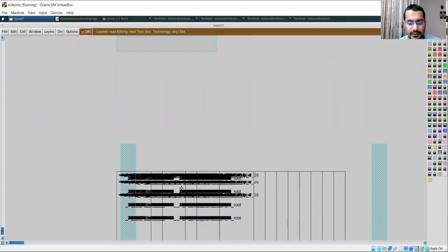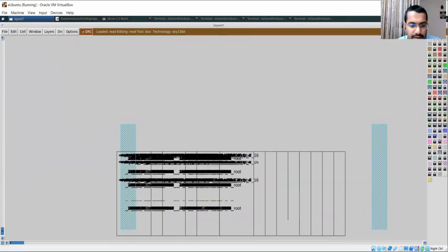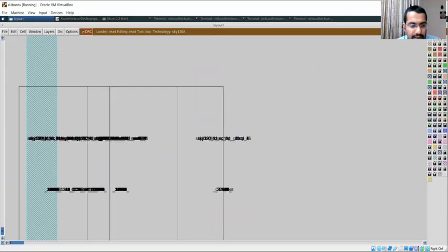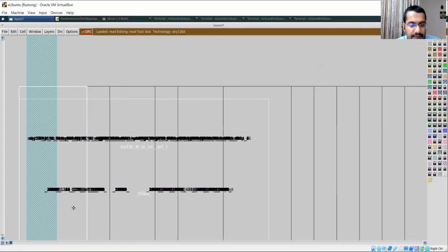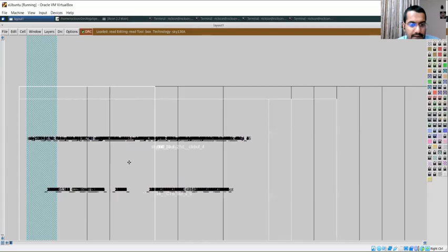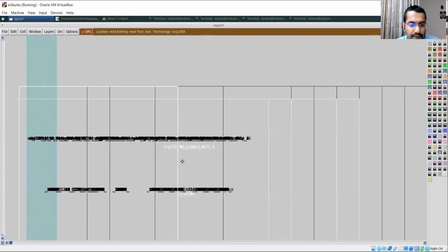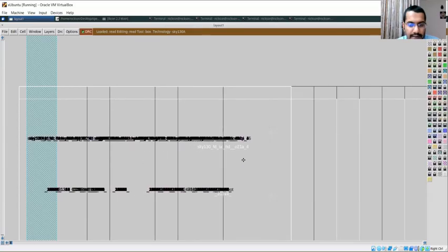So we will do one more zoom. I think we can see now. Okay, so let's see what these are. I will move over one of the boxes. I will do an S. So it's already displayed there. Sky130 buffer. So this is a buffer. Similarly, this is a clock buffer. OR gate. So these are standard cells which have now been kept in the lower left corner.